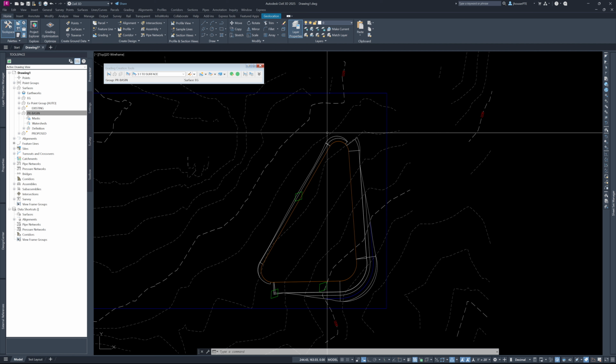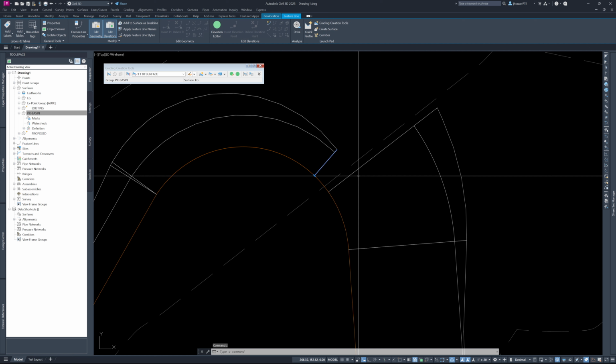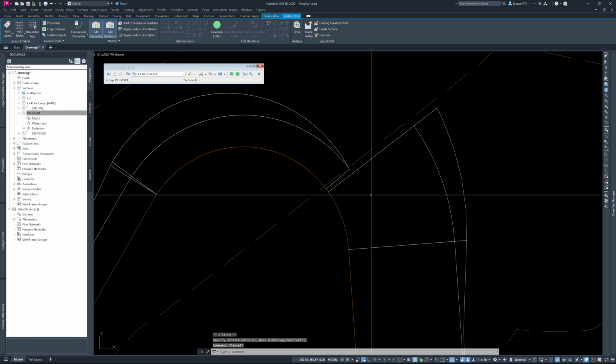Now you'll notice this contour right here doesn't really tie into anything. So that means that must be the, let me see, what is that? That's the 23 contour, 1223. Yep. What we can do is grab this end line here. See how it has a slider grip on there. We can slide that around until it gets past the existing surface contour, and there it ties right in.